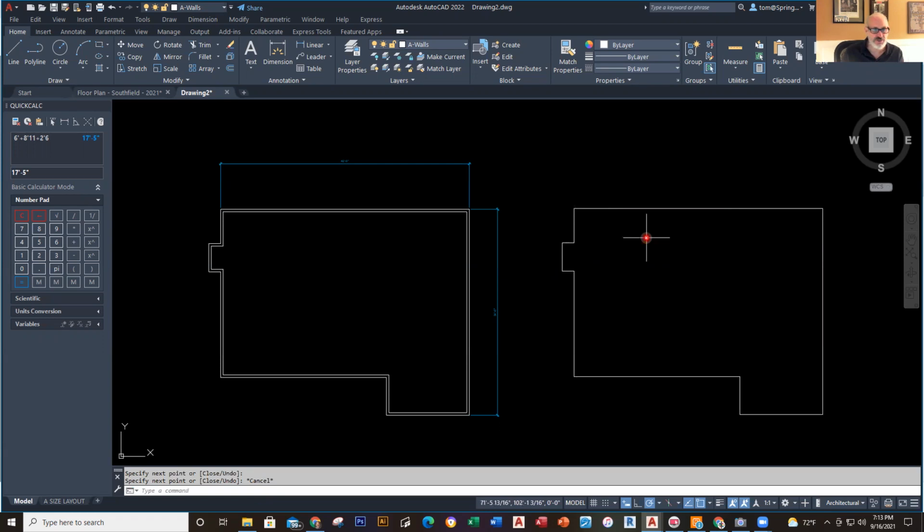Now at this point, watch what happens when I offset. I go to offset, and it asks me a distance, it's 5 inches. So I click on this and, oh man, AutoCAD sucks. Well, no, that's what happens if they're not joined together. Does that make sense there?